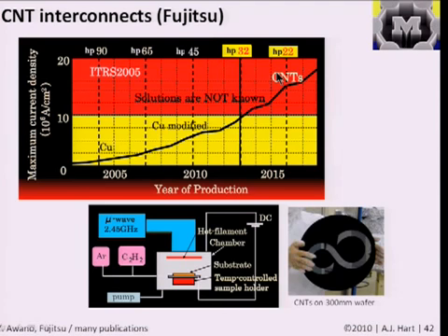So more or less the idea is that because carbon nanotubes have greater stability, because they're much smaller channels that can handle electrons, and because they can carry higher amounts of current without breaking down, if you could integrate them in this high density fashion such that they're all very densely packed, you could make a material that would overcome these limitations to use of copper in interconnects.